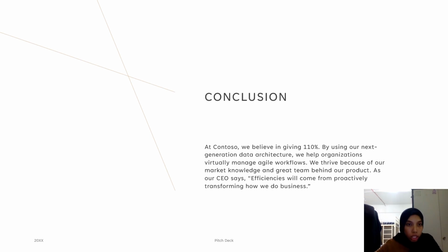In conclusion, it is discovered that different aerofoil angles produce different lift and drag forces. Because different applications require different lift and drag forces, we are unable to provide the best solution. Additionally, we draw the conclusion from the experiment that surface roughness will influence the boundary layer and the Reynolds number. A rougher surface will result in a thicker boundary layer and a lower Reynolds number. This is because the viscosity effect has become significant and there is increased shear stress on the rough surface. The boundary layer will become thicker and the fluid flow velocity will decrease as these factors become more prevalent.